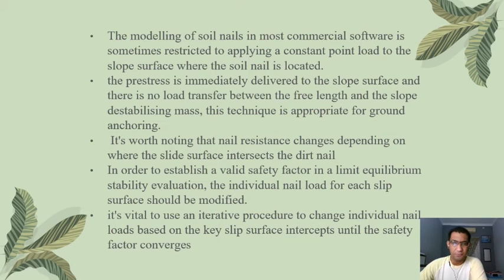The modeling of soil nails in most commercial software is sometimes restricted to applying a constant point load to the slope surface where the soil nail is located. The pre-stress is immediately delivered to the slope surface and there is no load transfer between the free length and the slope destabilizing mass. This technique is appropriate for ground anchoring.